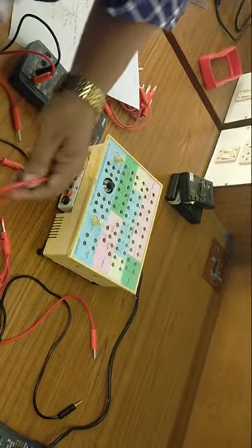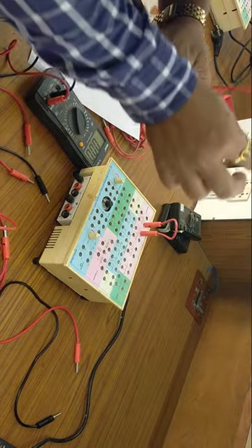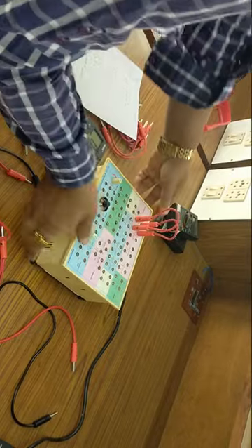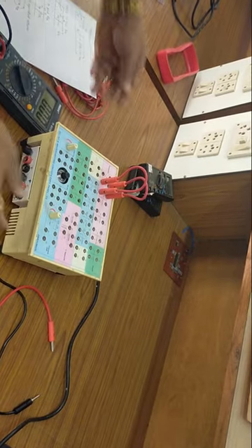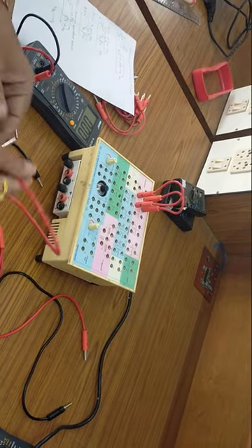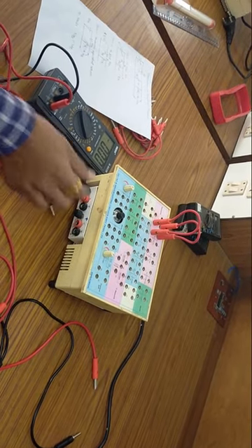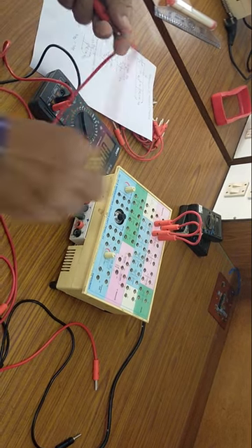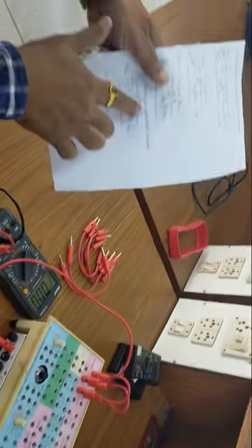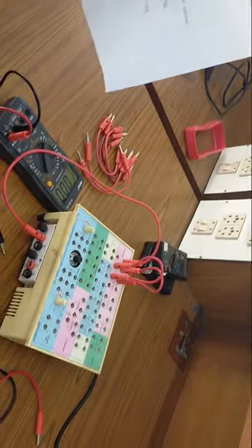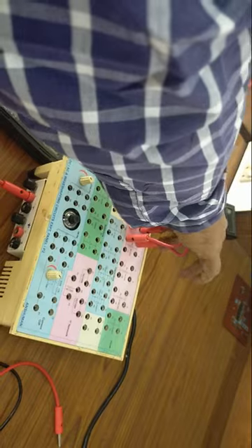Now let us make the parallel connection. R1 and R2 are connected in parallel, because we have to get 0.5K. You will find this combined value is 0.5K. Now ETH is adjusted. ETH is connected to one end of RTH. This is one end of the RTH, the parallel combination. ETH is going to this, and then the other end of RTH is going to RL.